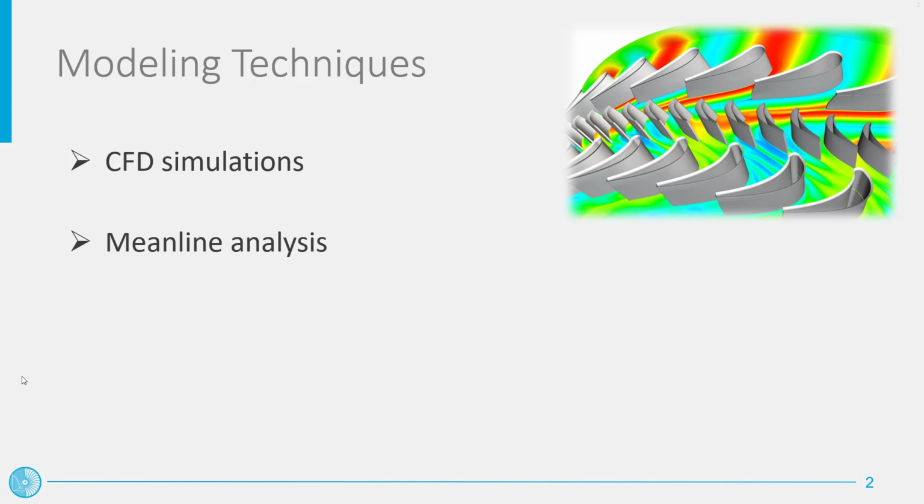The tools to build such a model are the balance equations of mass, energy, and momentum, alongside an empirical loss model to evaluate entropy generation inside the blade channels. Thanks to these dramatic simplifications, the mean-line model allows for quick determination of fluid dynamic evolution over the entire machine.